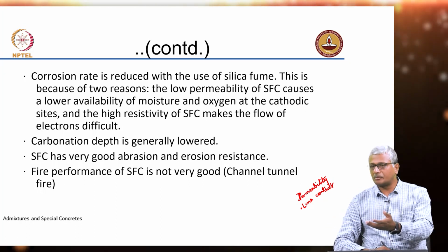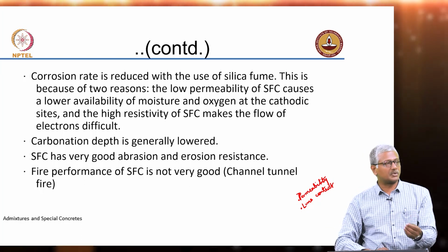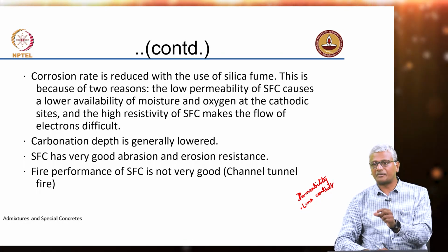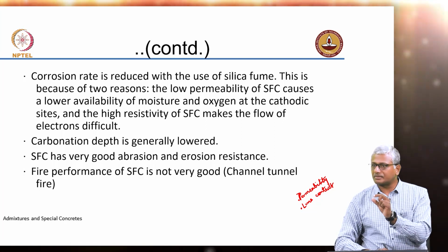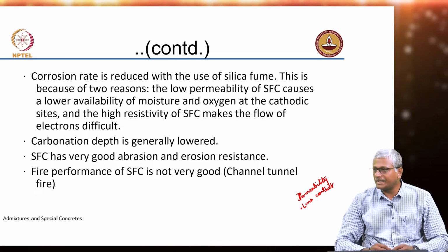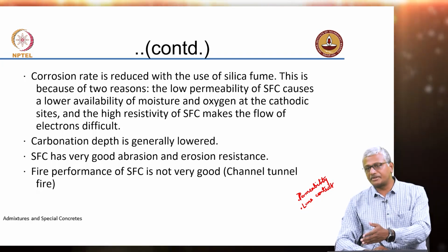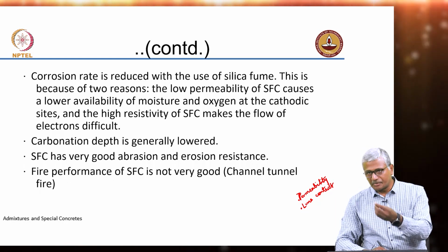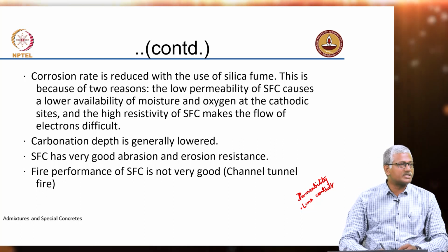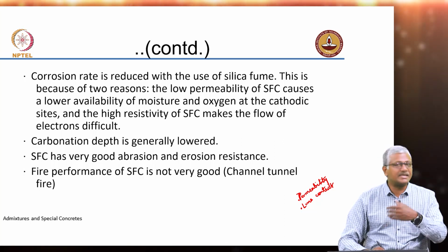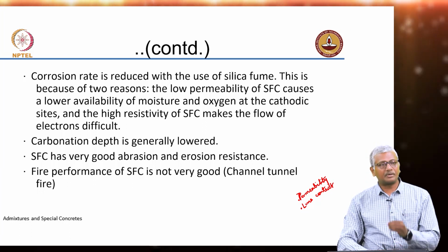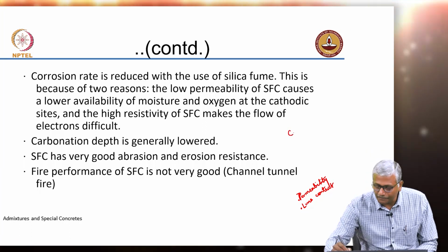Now, we talked about this earlier that when your system is lime rich, when it has more calcium hydroxide, the calcium hydroxide starts forming calcium carbonate, and that almost forms a barrier on the surface of your concrete through which CO2 cannot further penetrate easily. But whenever mineral additives are used, since calcium hydroxide is not available in large quantity, right, your CO2 is able to penetrate into the CSH or other calcium bearing compounds. CSH also will start carbonating, and carbonation of CSH leads to more porosity.